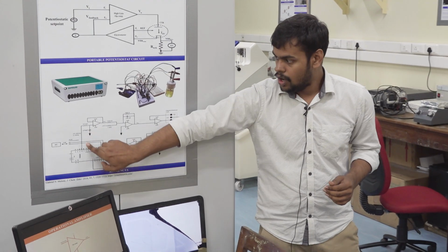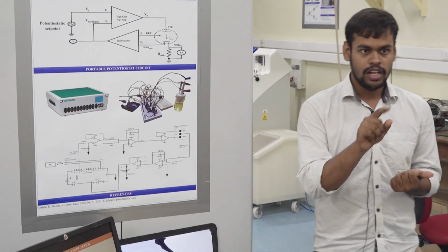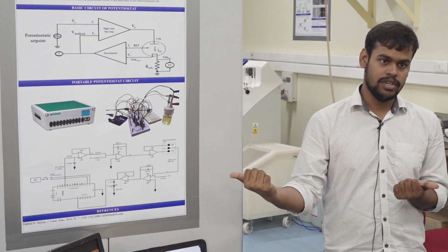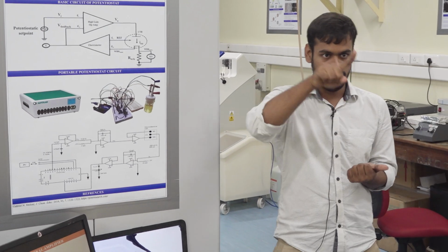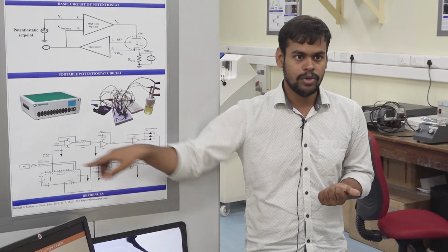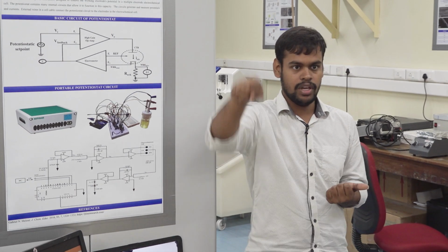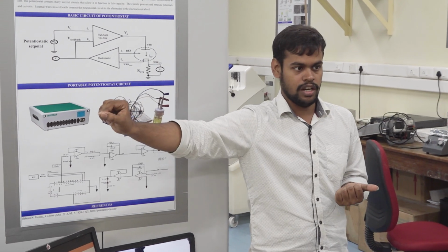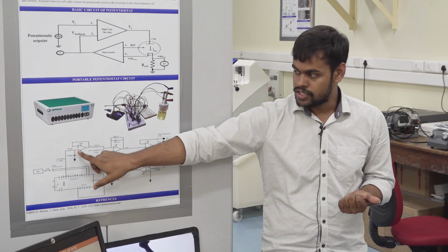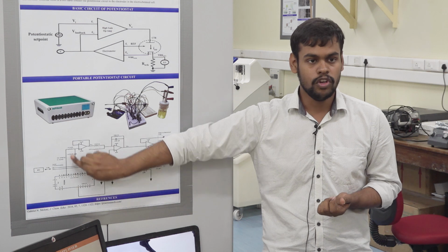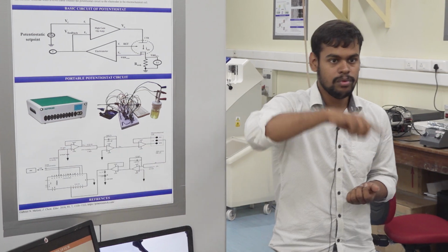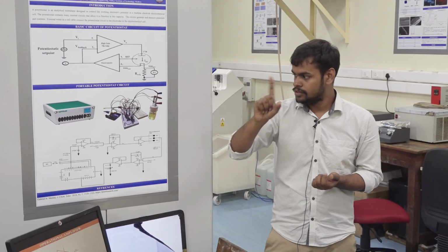Now, when you apply a potential, you need it in a certain way, because this is a DC measurement we are doing right now. So it should be a straight line. It's not sinusoidal. So the RC filter will take whatever pulse width is coming and convert it into a straight line. Now, the straight line conversion has happened. This part involves the Arduino. From the Arduino, you will get a signal that will be in a ramp function like this.